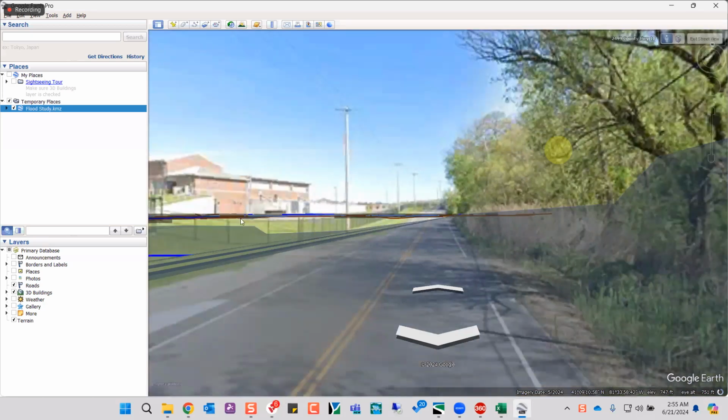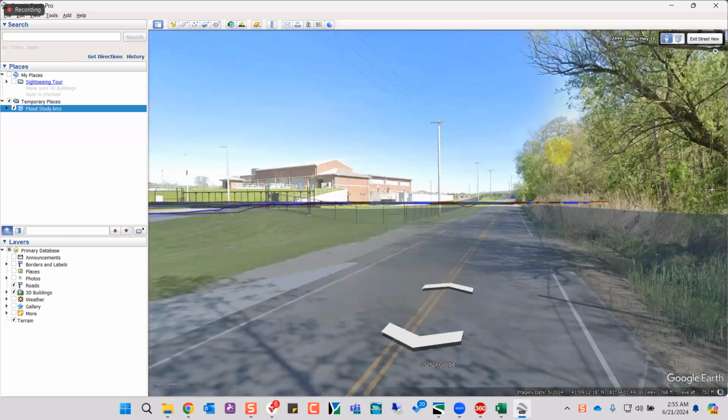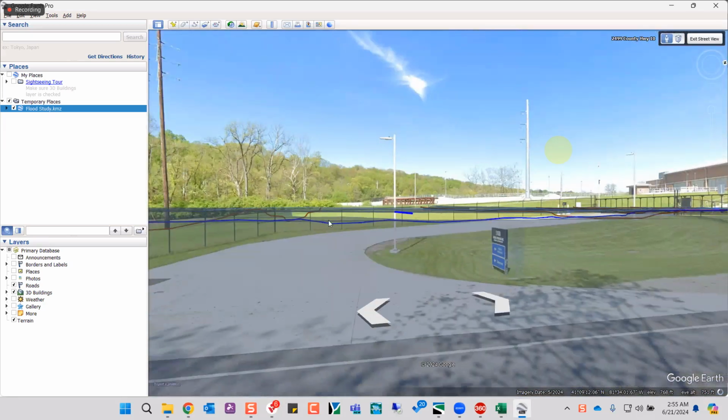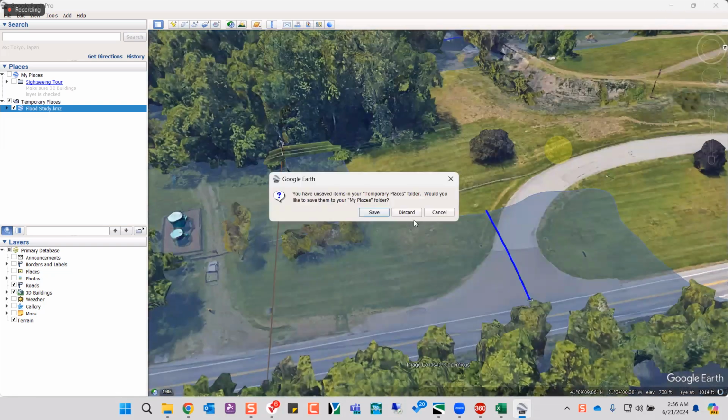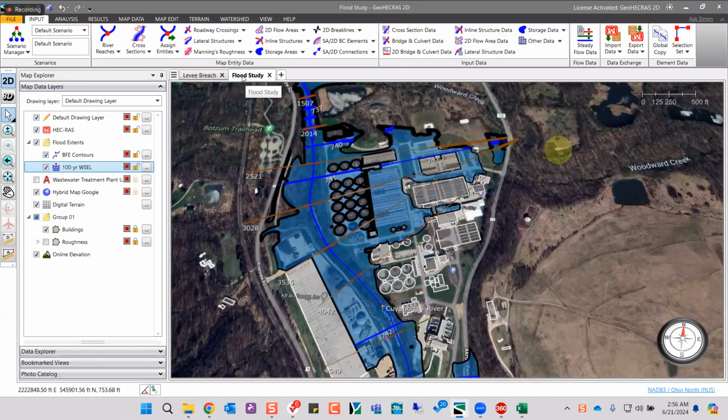There you go. Now, this right here is the real game changer. Your clients would think that you spent hours and hours on creating this flood map in Google Earth. Well, you guys, you do not have to tell them that you simply click the button. Anyway, let's exit out. With this, our 1D model is done. And to export this model out to HEC-RAS, you also have a shortcut wherein you can right click on the file name and choose open in HEC-RAS. It directly exports your model out to HEC-RAS with one click.